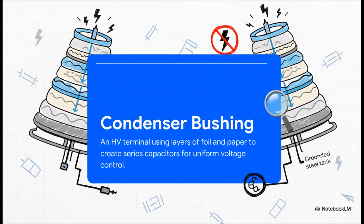Getting that high voltage safely out of the grounded steel tank requires another incredibly sophisticated bit of engineering: the condenser bushing. By layering conducting foil and insulated paper, it effectively creates a series of capacitors. This whole structure acts like a voltage divider, making sure the potential drops gradually and uniformly from the central conductor down to the grounded flange, which prevents a catastrophic electrical arc.